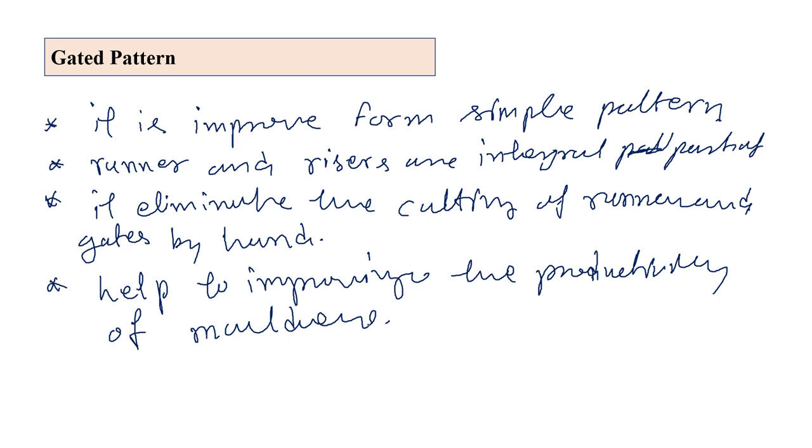So this is the gated pattern. The gated pattern is an improved form of the simple pattern. Runner and risers are integral parts of this pattern, and this completely eliminates the hand cutting of the runner and risers, and improves the productivity of the modelers.